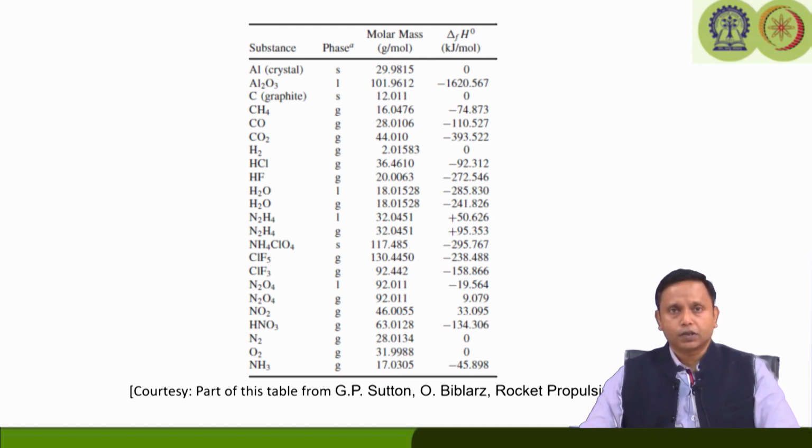We also talked about the density of the propellant, which should be high enough so that we can choose a small volume motor, because we want a compact motor, and we all know that the rocket is a volume limited propulsive device. The volume is restricted, so we need to use a high density propellant to make the motor compact. Okay, up to there we have discussed.